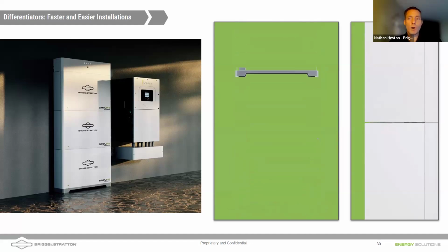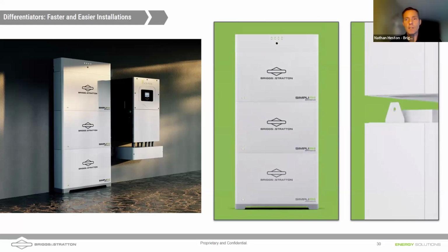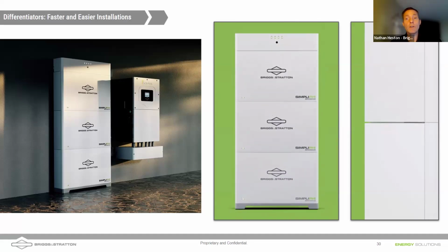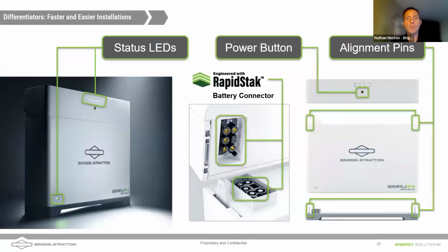This would cover my home for a full day. You can also do multiple stacks of batteries. One of the nice things about these batteries is how quickly they assemble. You're seeing a marketing GIF on the right side of the screen with it coming together. It really does stack like that, but there's a little bit more to the installation. We have brackets that hold the battery to the wall so it doesn't tip over, or in the event of something like an earthquake or somebody standing on it, prying on it. We want to ensure that our battery is going to be safe. That being said, don't stand on the battery. But you will have some wall brackets that I'm going to discuss in a minute.